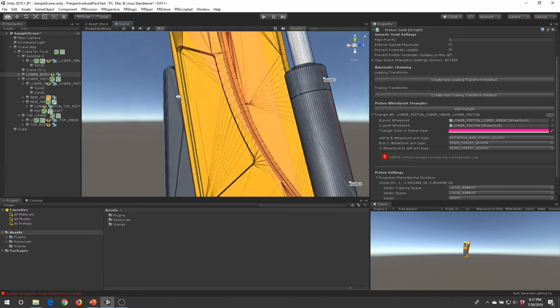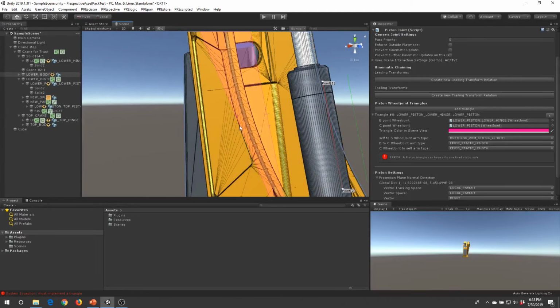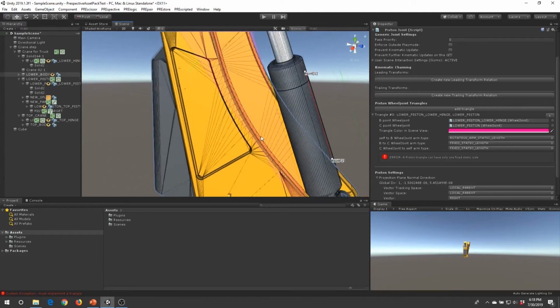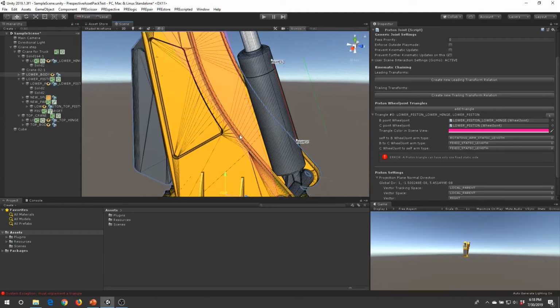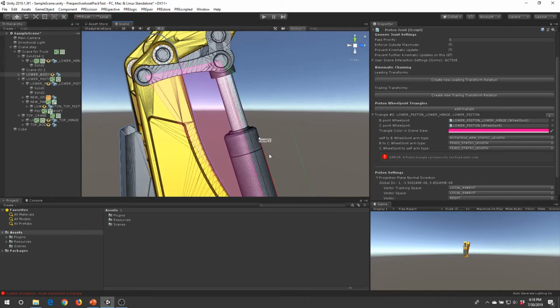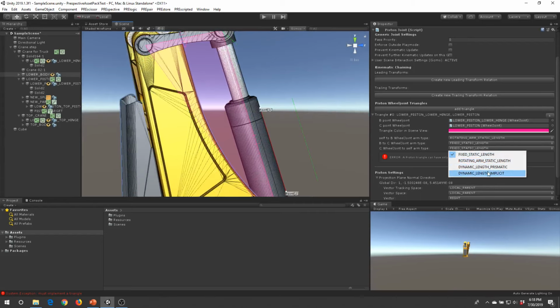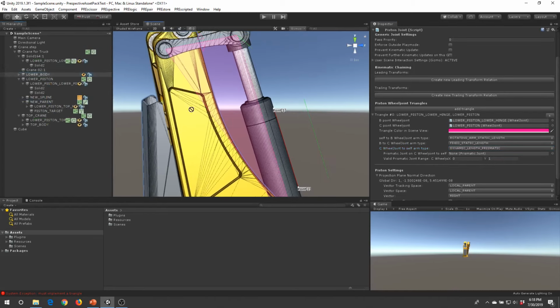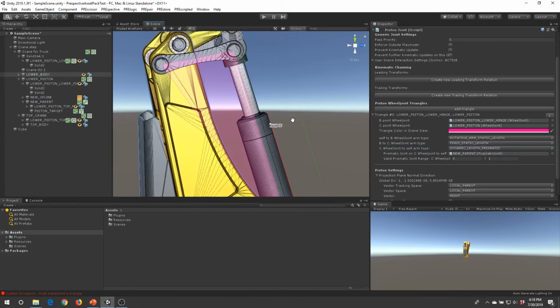Then the second part is actually static in length and static in position, which is what this icon references towards and is okay. So fixed static length, we can leave that there. And the third part is actually we're using a prismatic joint. So we'll say dynamic length and prismatic. And now it will also prompt us to add in the prismatic joint we have over there. So let's put that in there. So that's the first triangle.